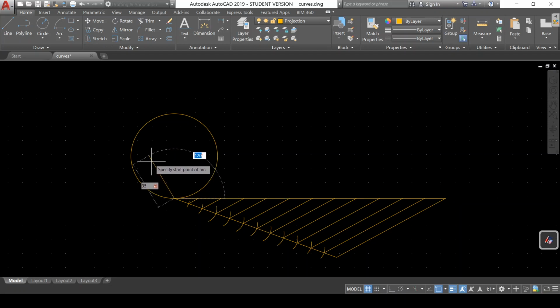So it is easier to draw the locus of the point P if you choose it on the left side of the center axis. So I choose the point P on the left side of this vertical center line. Choose it here, 35 mm. So P is here, 35 mm from this contact point. So this is my starting point. I have to trace the locus for this point P.